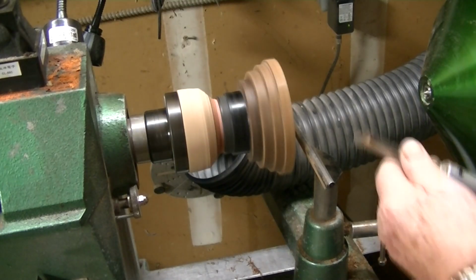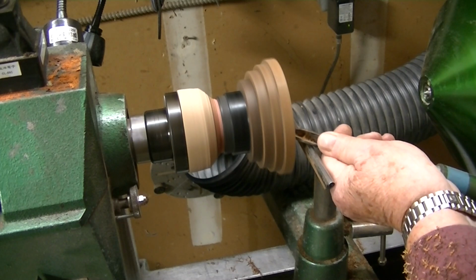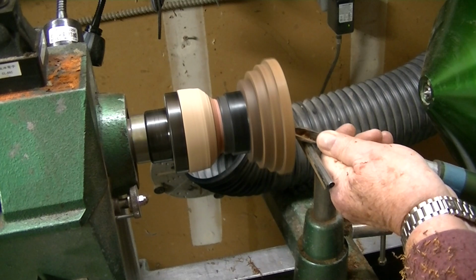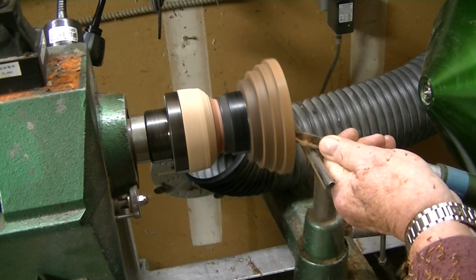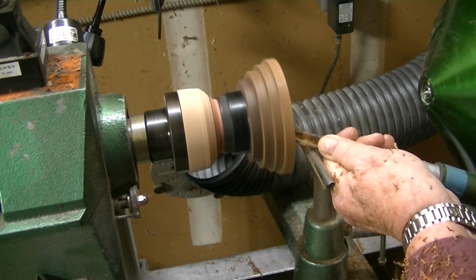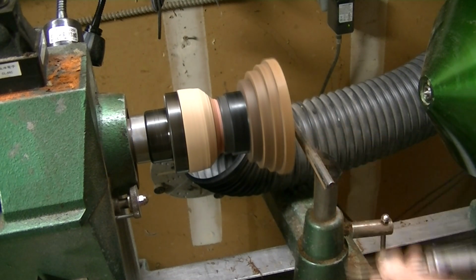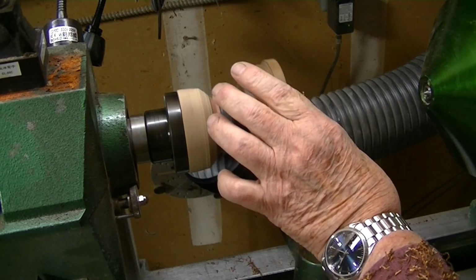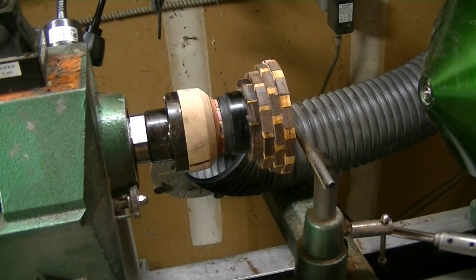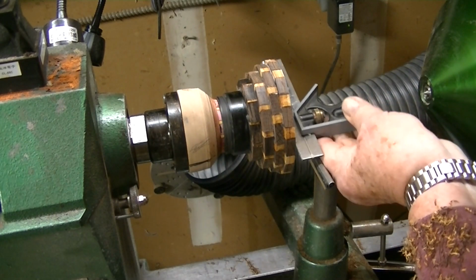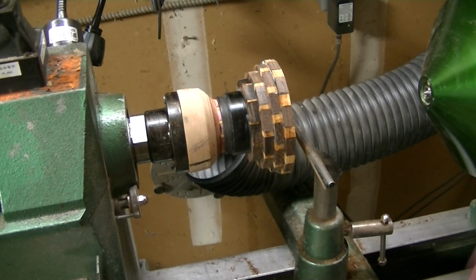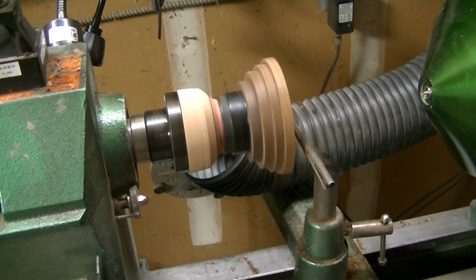So what I need to do first is to be sure that the assembly top is also dead flat. So a few passes with the bowl gouge to clean up any surface there. As soon as I'm certain that that is as flat as I can get it with a tool, I'll check it with a square. Fingers first. Square will let me know whether I have the edge pretty near flat. If it is, onto the thing I always end up with, which is a sanding stick.